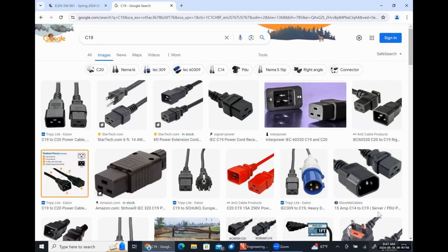All of their amplifier heads have a switch on the back that you flip to configure it for North American or European power, and it literally just uses a different plug. You switch things over so that the tubes are biased correctly for that particular place, and then connect the right plug to the outlet you have. Most modern electronics are designed to be used in a global marketplace. So anyway.